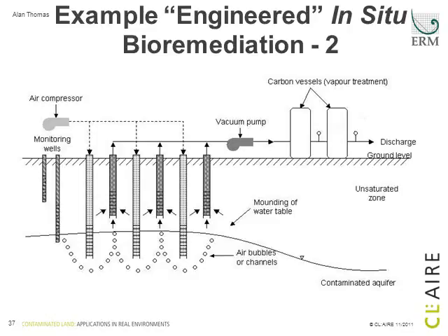Another example, this is an in situ biosparging type scenario, where we inject air into the subsurface, into the contaminated aquifer, introducing oxygen, as well as probably in this example some physical stripping of contaminants as well. You can see there's a requirement for off-gas treatment, but just another physical variation of in situ remediation.